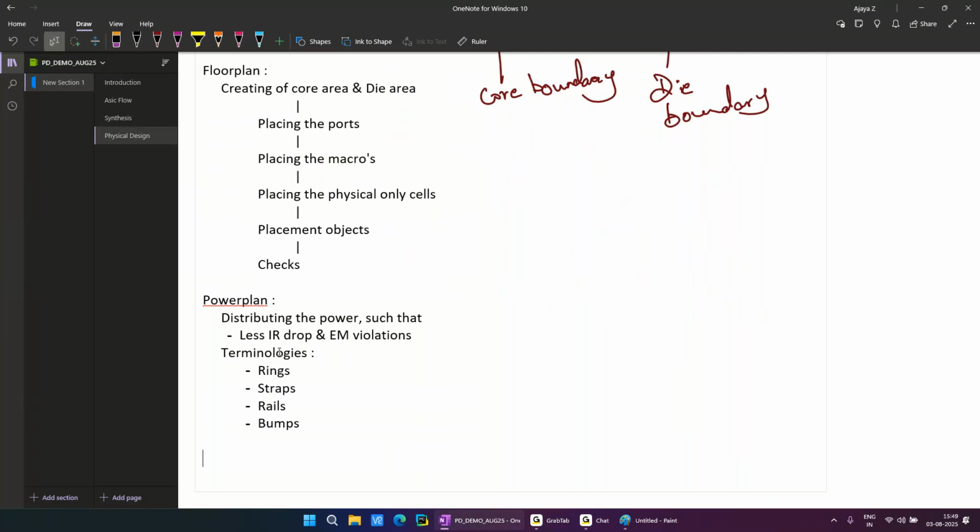If there are fewer, you will have voltage drops to fix. So I have to focus on all those algorithms and design that strategy properly, which means it takes more time. That's why, as a PD engineer, you will not focus on developing the power planning. You will just source it. If you face any issue, then you will discuss it with the power team and get it fixed. There is a separate flow.